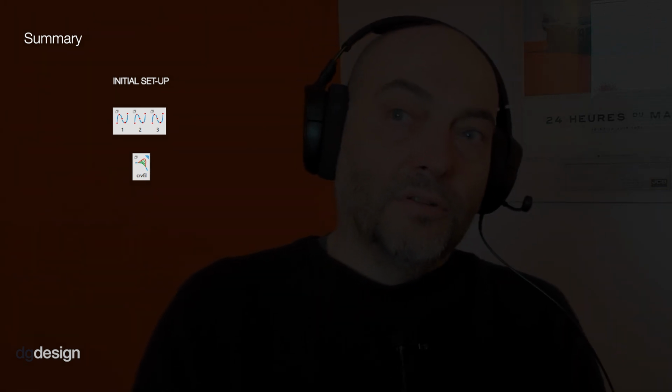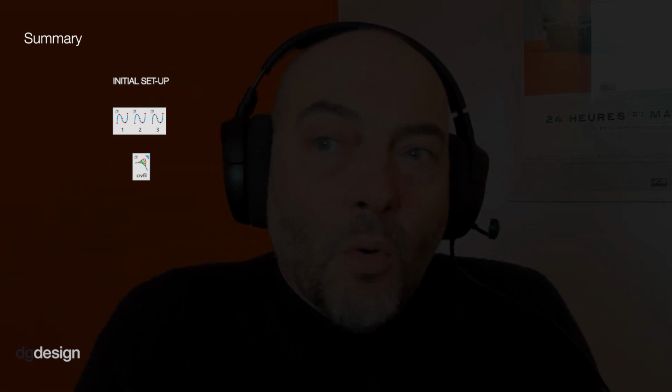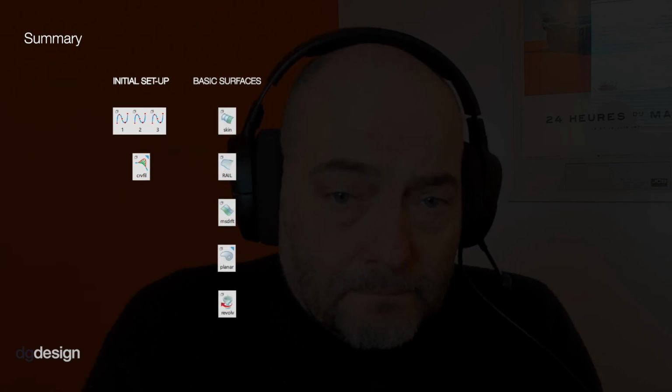As far as the initial setup goes, yeah, I'm using very low order curves, G1 through to G3 typically, to get the main slabs up and running. You can go higher if you want, you can have more complex curves, but generally I like to keep my surfaces really simple and light, and not have the surface having to change direction too much. You know, to me, if it's got to wrap through 90 degrees, chances are there needs to be another surface in there rather than one surface with a complicated flick at the end.